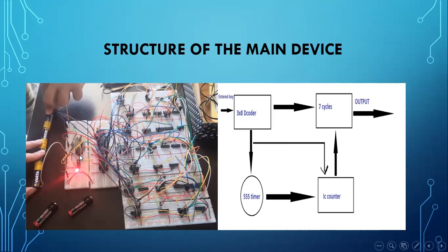So basically, if the signal from the device is similar to the signal from the user, it means the password is correct, which is going to send a signal here to the green LED. The same signal also goes to the NOT gate, which means if it's wrong, it's going to be low going into the NOT to make it high, because we know both LEDs must have a high signal in order to start. So that's why it's like a simple formula outside of the box here.